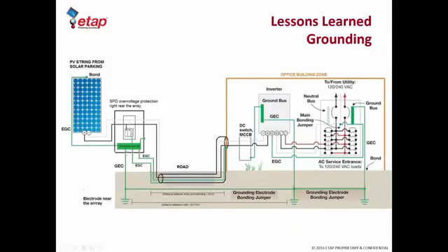That itself was connected to the structure ground and grounded, and the equipment ground was carried through and brought into the ground of the inverter, which also is grounded back to the actual switchboard. The voltage shown is incorrect, it's actually 480 volt, and everything is bonded together through a common UFER ground. So that's essentially what we learned on the grounding side.